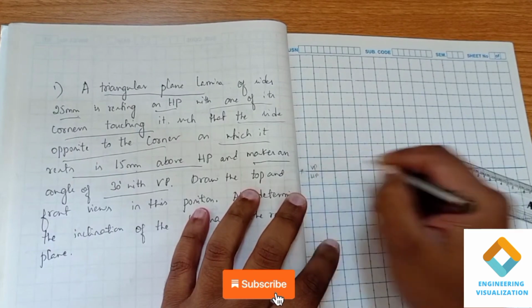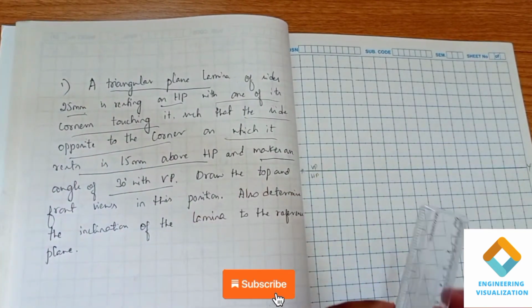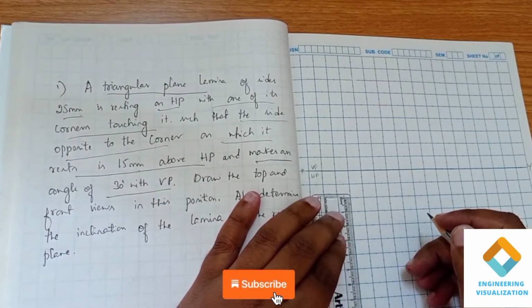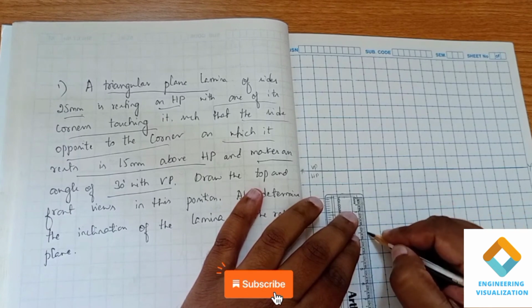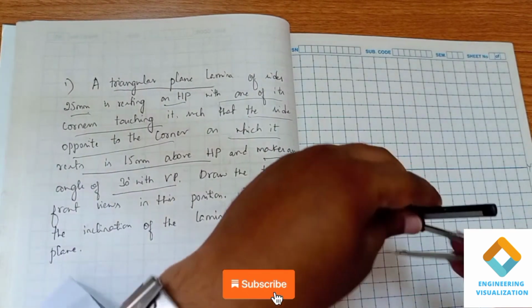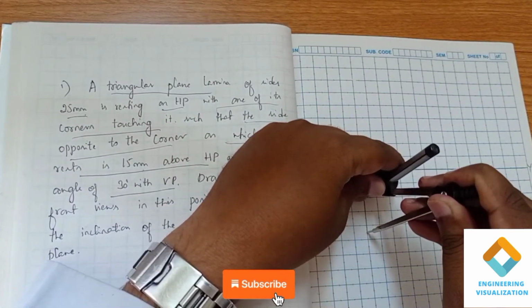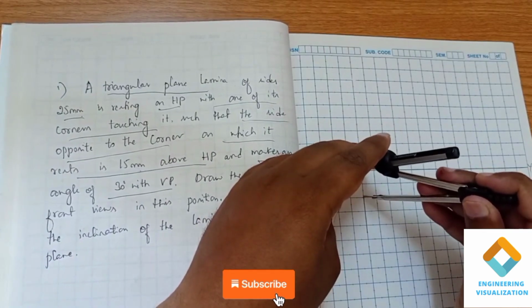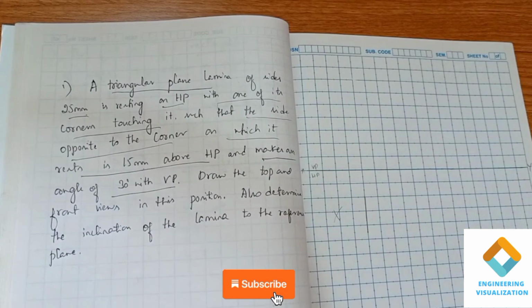Good morning. We will see another different type of problem in triangular lamina. In this type of problem, we have to construct a triangular plane lamina of dimension 25, resting on HP and with one of its corners touching it. So the first position, we have to construct a triangle with the corner on the HP plane. Now in this problem, we have mentioned that the side opposite to the corner on which it rests is 15 mm above HP.